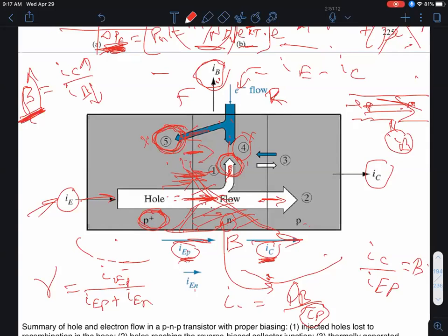Well, you can apply that same kind of principle to the BJT now, where this is my stored charge in the base. And suppose I'm looking at a steady state DC current. I have to maintain a steady state charge distribution QB, which will be nothing but the integral under this distribution divided by the lifetime. All right. That will give me an expression for component 4 of the current, right? Because that's the rate at which carriers are being recombined and I have to replenish them at the base. So that's this component 4 of the base current.